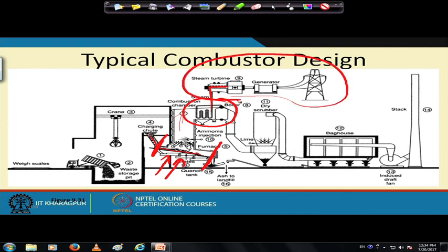So that part is the energy part. And from here, the ammonia injection will control the NOx. And then you add lime, you have the dry scrubber, you have the baghouse, and then you should have an electrostatic precipitator somewhere now. It has to be there.